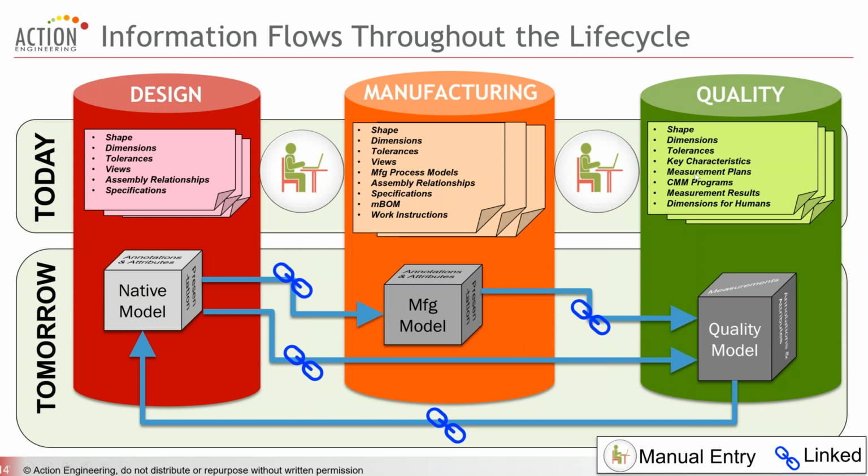creating more modernized bills of characteristics, measurement plans. QIF has a huge impact on CMM programming to really greatly streamline that process. But then you also need a data package of quality where your measurement results can then carry this information back to manufacturing and design so that they can improve their future designs, existing designs, and improve their manufacturing processes.